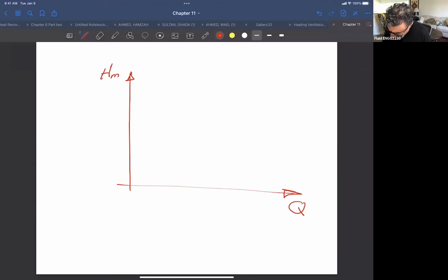So this is a manometric pressure, and all the curves of the centrifugal pump will follow the same kind of shape, right? So this is a relation between the manometric pressure and the flow rate. And this is all at the same RPM. Okay, so for the one RPM, you will see this curve going like this. So for zero flow rate, you still have a head that is not infinity or so high, it is limited by a certain value for a centrifugal pump.